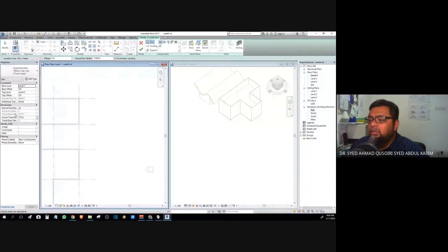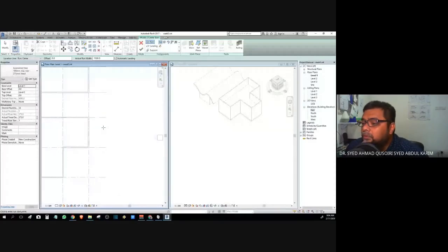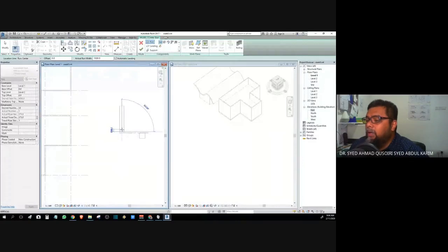Let's say I want to build the stairs here. This is not a house, more like a warehouse. So this is just plain drawing. As we click and then move the mouse, Revit will tell us how many steps have been created and how many are remaining.